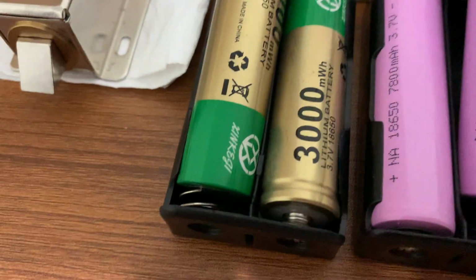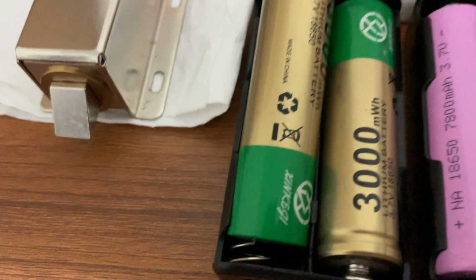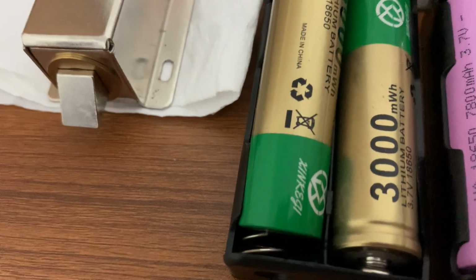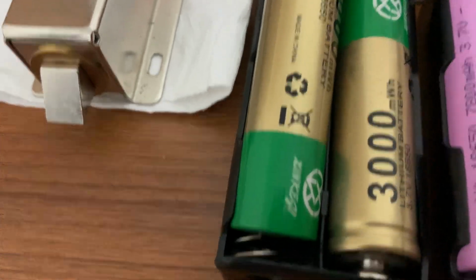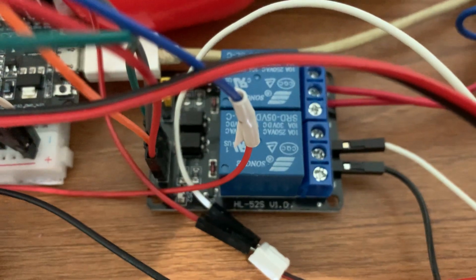To power this 2-channel 5-volt relay module, I have used a pair of batteries that supplies around 8 volts, and the module has a rated voltage of 5 volts. So the voltage generated by this pair of batteries in series has to be stepped down, and I've used the LM7805 linear voltage regulator. The output of the linear voltage regulator is 5 volts, which is directly fed to the relay module to